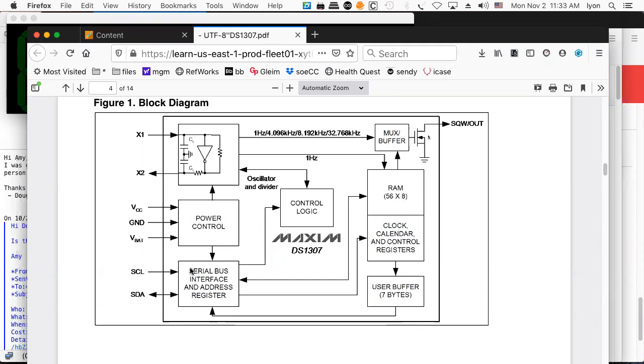And I think it's important for us to consider that if we're in the course that allows us to interface everything to everything, well, we have to recognize that there's more than one kind of bus. SPI bus, which is high speed, and maybe has a few extra wires, or I2C bus, which is lower speed, but has fewer wires. And so that's kind of neat. It's also a bidirectional bus, and it uses addresses, so that's cool.